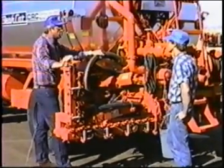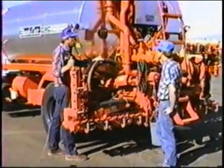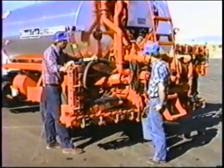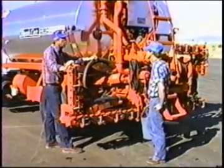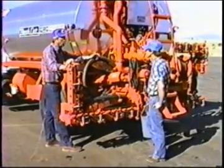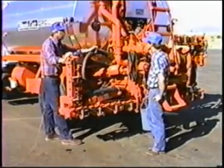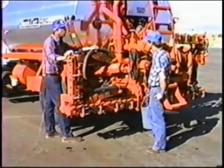The computer sees the spray bar width from the control panel. That is, if we have 16 switches turned on for this spray bar, it reads that as being 16 feet wide. It takes those three numbers and calculates them together and decides the required gallons per minute in order to create that spread rate at that particular speed at that bar width. It determines the gallons per minute required, and adjusts the asphalt pump to that based on information that it sees here on how fast the asphalt pump is turning.